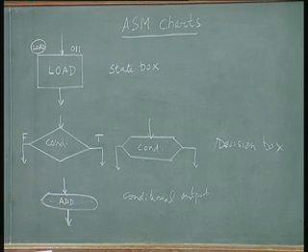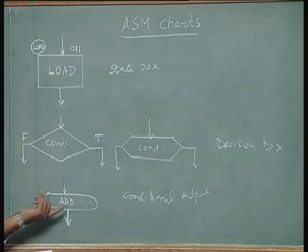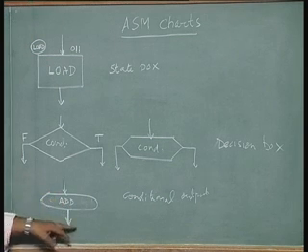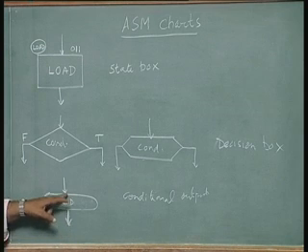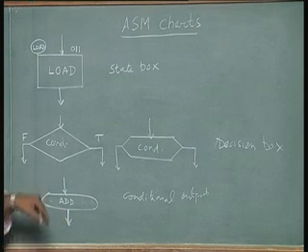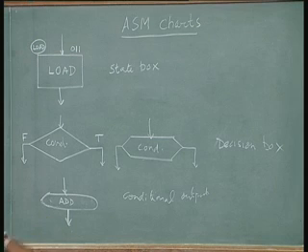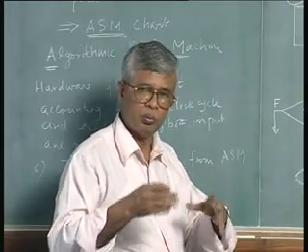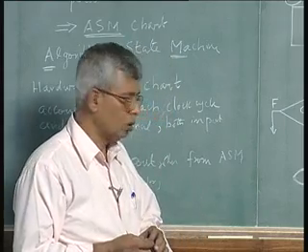This is useful. Otherwise, what we have to do is to put an extra state. Now, after this it can go to this, generate this add signal and go to the next state. If you do not have the conditional output, I may have to put one state for add and then next state one more state for shift, which means I will put one extra state. If you keep adding the number of states, the mapping hardware becomes more and more complex. So, to avoid that we have this.